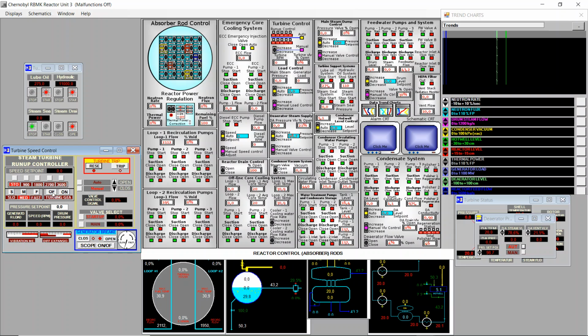Now it's reset, and turn on the turning gear. We see the speed set point is increasing now. This number increasing here, 5, 6, 7. When it reaches 20, the turbine will be in turning gear.